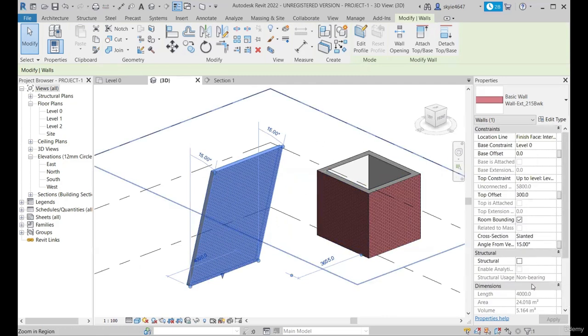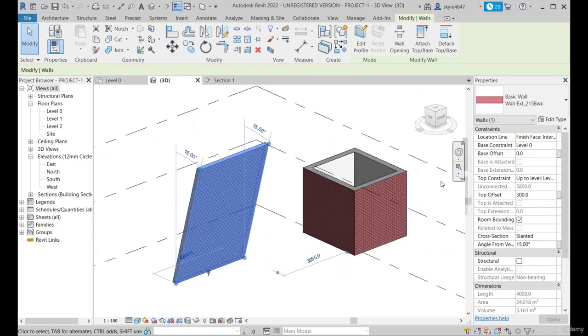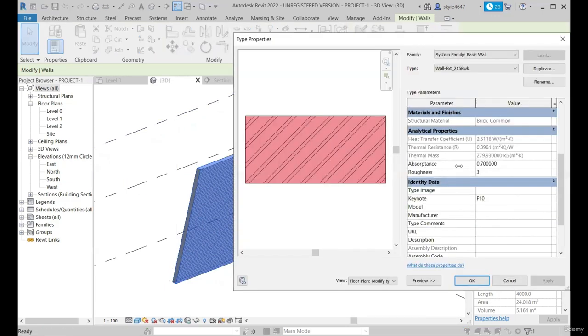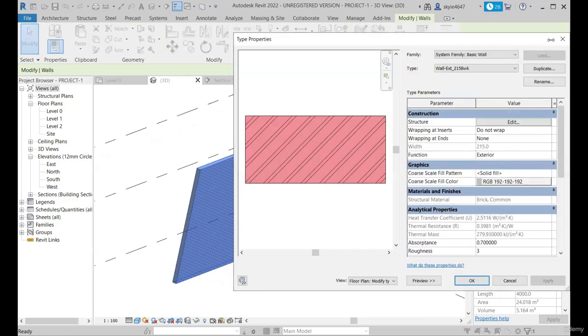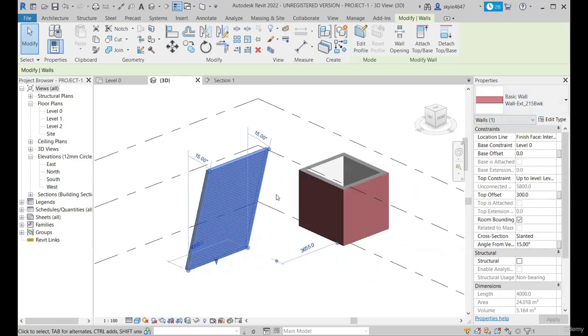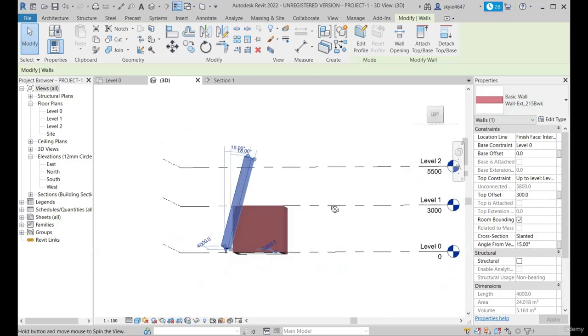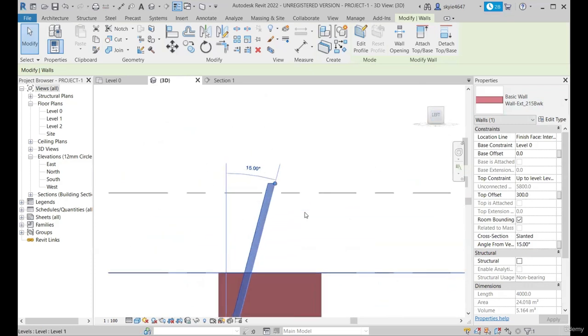These are instance parameters and are dependent on a single entity. If you want a single change to be reflected everywhere in all walls of a type, then you need to go to edit type. Any changes there will be reflected to all the elements of that particular wall type. Let's not worry about it now; we will brief it as we progress through the course series.